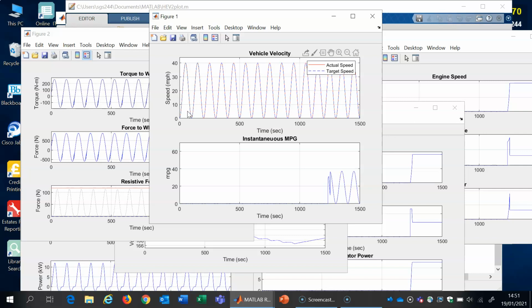So you have some initial energy there, and then during braking it charges the battery as well, so that the kinetic or mechanical energy of the vehicle during braking is actually fed back. Then you can tell the vehicle only starts to consume gallons of petrol from there. Okay, so that's the first graph.